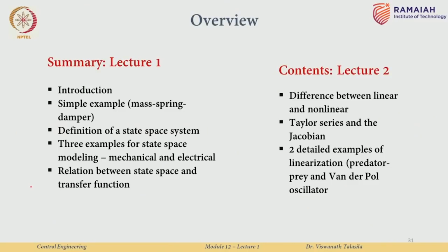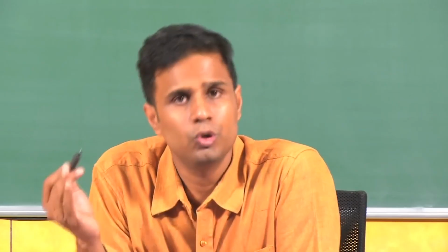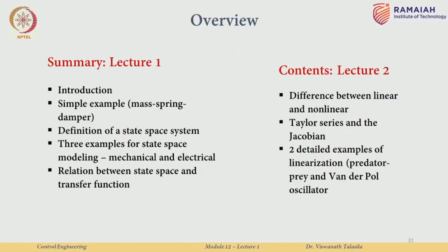So what we have learnt in this lecture is that we introduced the concept of a state and a state space system, and we saw why state space systems are very important. They can model nonlinear systems, they can take care of multi input, multi output systems, and so forth, which the transfer function approach could not easily do or could not do in some cases. We saw the basic form of a linear time invariant state space system, x dot equal to Ax plus Bu and y equal to Cx plus Du.